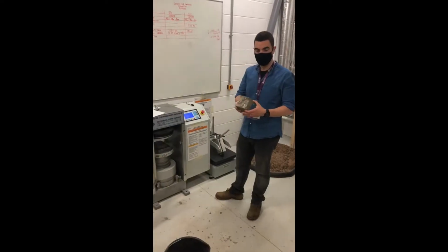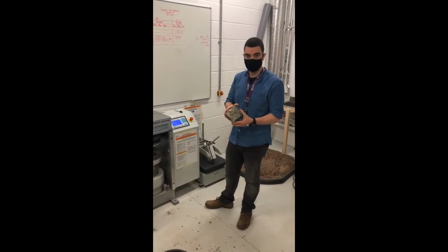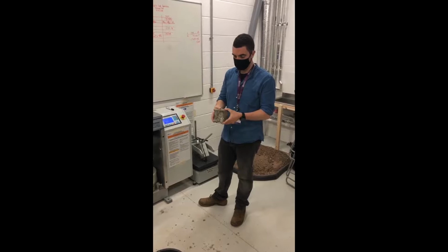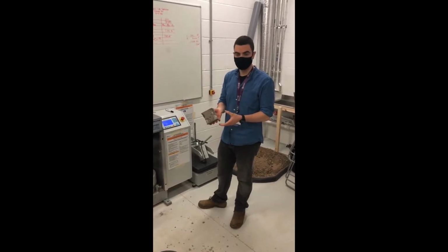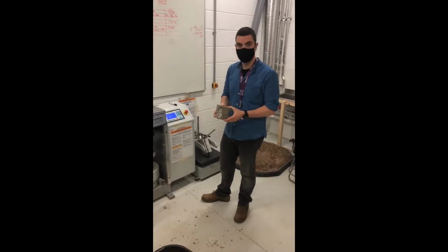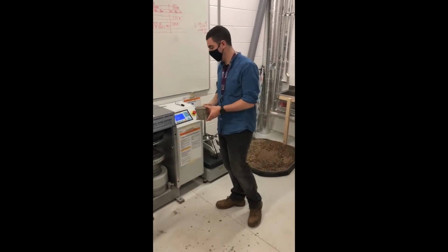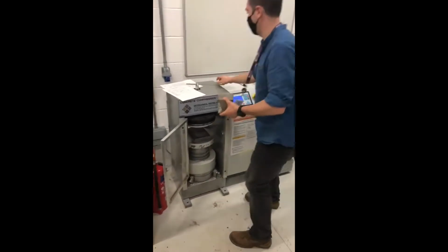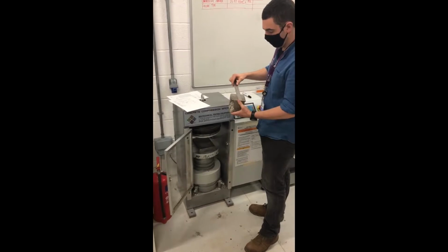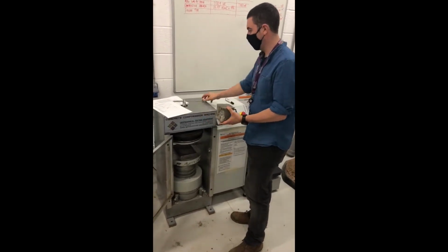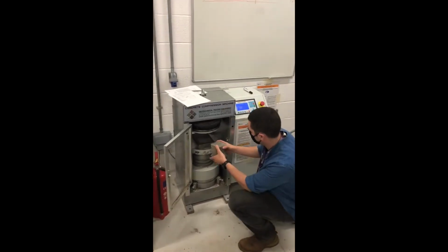So we're going to test the residual compressive strength that's remaining in this cube. It's obviously experienced failure, but there's still some strength left within it. So we'll put this back into the machine and see what force we can get. First of all, we'll take a reading, and you can still see we've got an area of 100 by 100 on that surface.